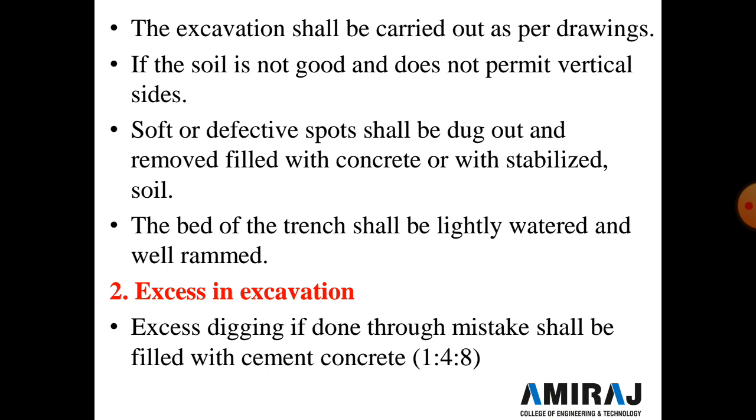And the second point is excess in excavation. Excess digging, if done by mistake, shall be filled with cement concrete of ratio 1:4:8 at the expense of the contractor. No extra payment shall be made for this.